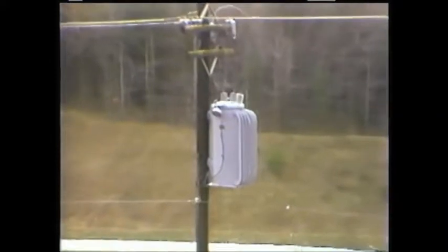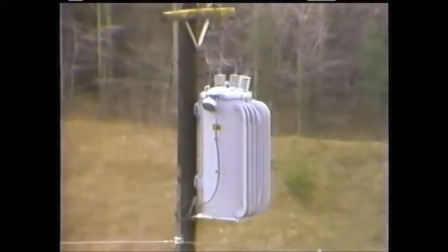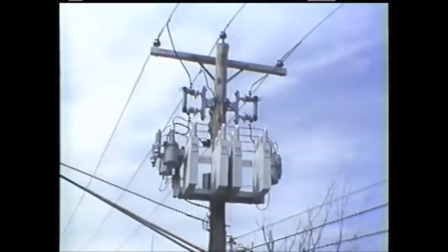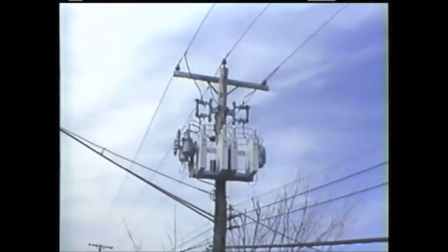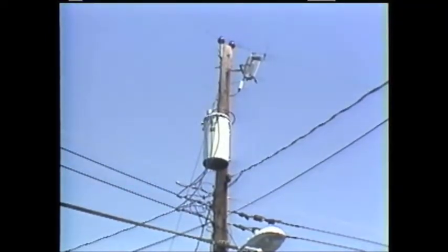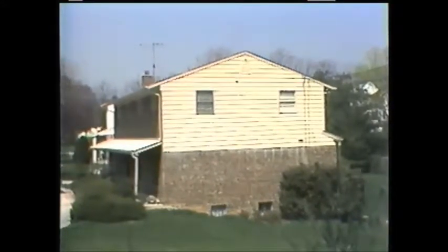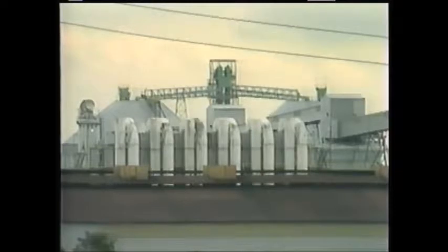A voltage regulator maintains primary distribution voltage within a specified range of acceptable values. Capacitors, which are generally arranged in banks, are used to increase the overall efficiency of the distribution system. Distribution transformers step down distribution voltage to utilization or secondary voltage, which is the voltage of the electricity supplied to individual consumers by service drops. Secondary voltage varies depending on the requirements of specific consumers. An industrial plant, for example, may have different voltage requirements than a residential consumer.